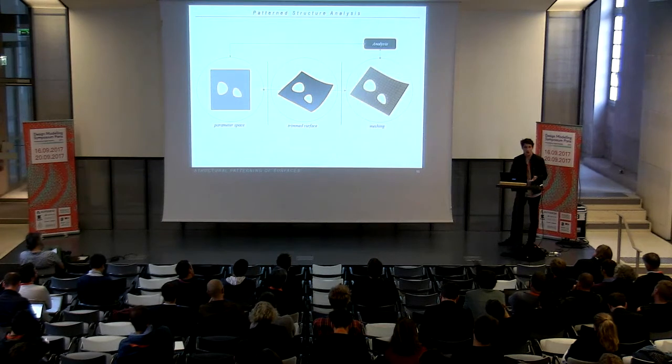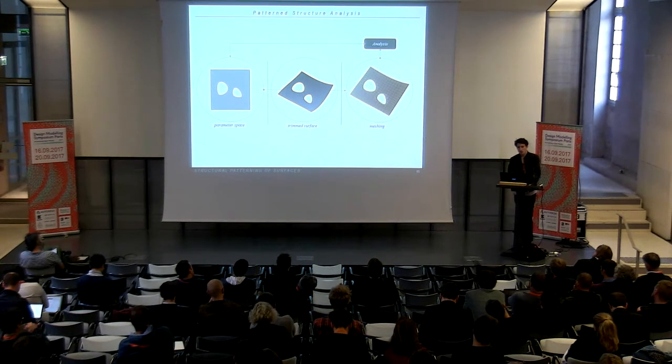Same goes for trimming. With our method, all the numerical legwork is actually performed in the parameter space. Therefore, we can fully describe the patterns in the latter, while the 3D trimming curves never need to be accessed nor manipulated by our algorithms. As a result, it allows to quickly exploit pattern variations in a performance-driven way.